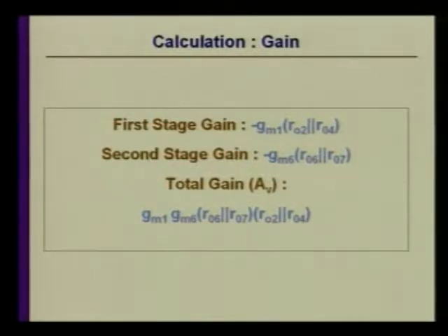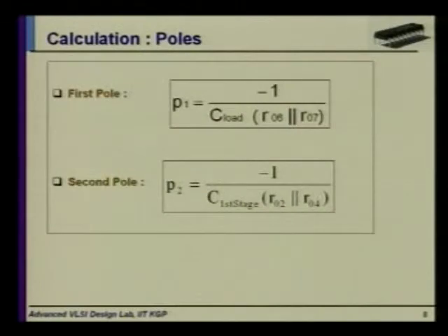So clearly you can see that we have already increased the voltage gain without increasing the length or width of any individual transistor, that is, without increasing the area of the chip. As we have introduced a new stage, we have introduced a new pole. These are the two new poles in the transfer gain.